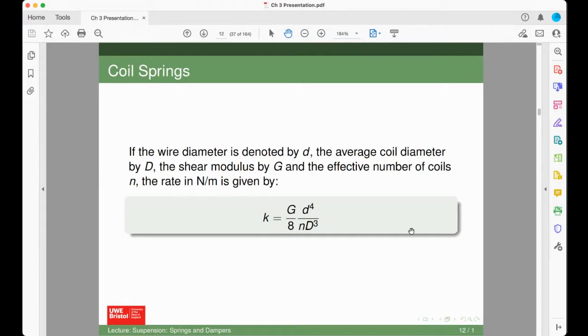With the progressive spring, there are pictures on page 26 in your notes. You can have different coil diameters, different wire diameters, which is picture B, and then in C you've got coil spacing, with coils that are widely spaced apart and then close together. And D is a mix of all those things: different coil diameters, wire diameters and spacing.